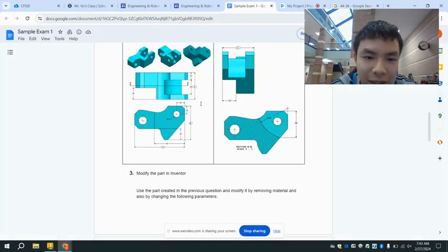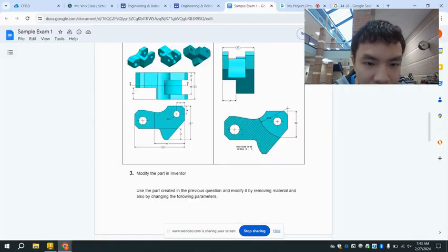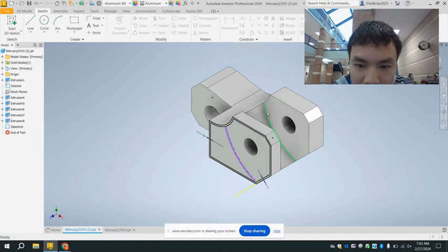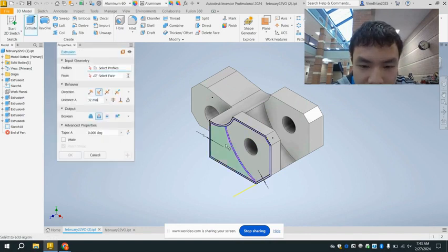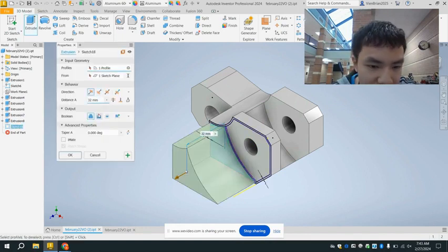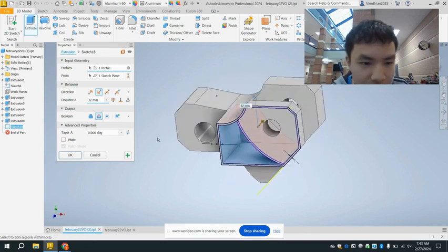Okay. So that means this part right here, where my cursor is, is 8 millimeters. So you do 8 plus 24 now, because you want to extrude to that back end right here. You want to extrude to only this end right here. So 8 plus 24 should give you 32, which means you want to extrude only this back. Make sure it's cut to 32. See, 32. You can click on OK, or you can click on Add.